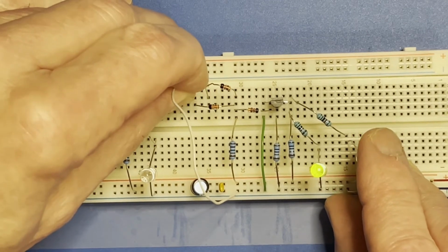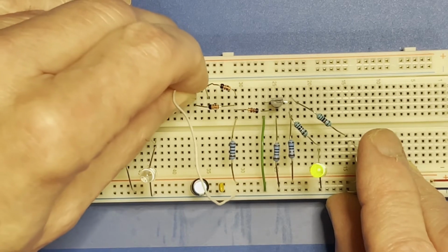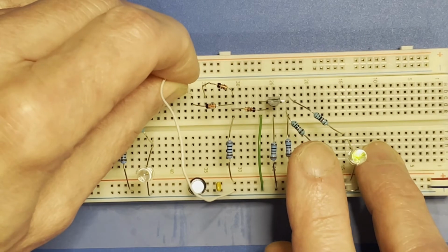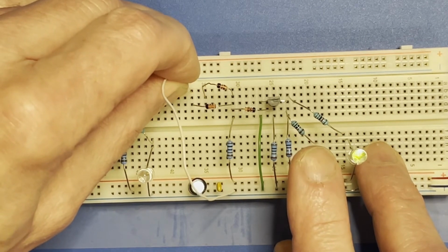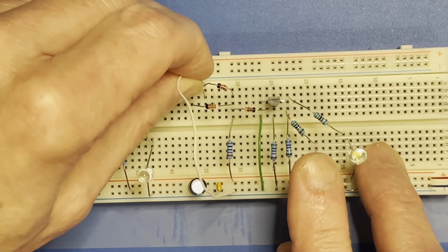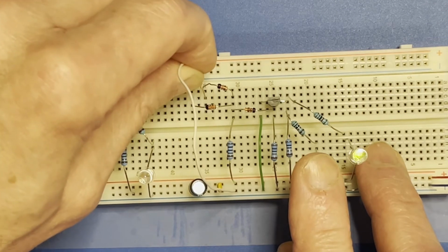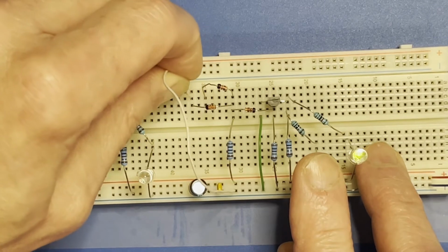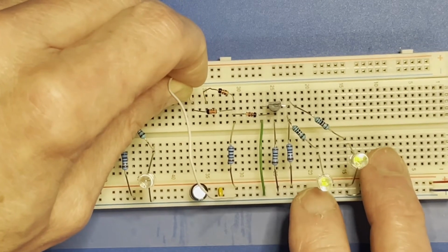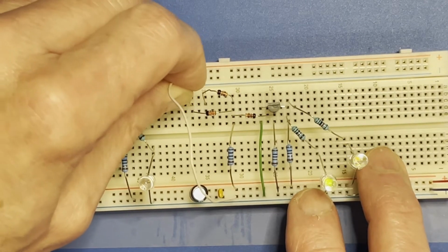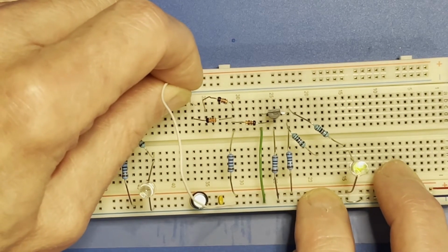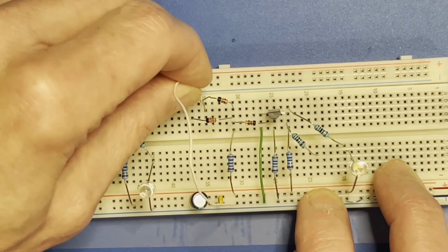Then the problem is then the person doing the demonstration will simply reconnect the LED, or have another circuit with the LED connected between the output and power, and then claim that's changed to an AND gate, which it hasn't. There's nothing different except how they're indicating the levels. That now does the same as the diode AND gate in a truth table sense, or ignoring the circuitry and looking at the indications. So either input being switched to low, the output goes low, apparently, but it's not. They're just reconnecting the LED. That's the center, the proper output, if you like, indication, that's on when the output's high. And just to verify, if I take that LED out, it doesn't magically change the circuit operating mode. Change the indication, and that's all.